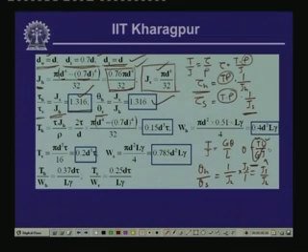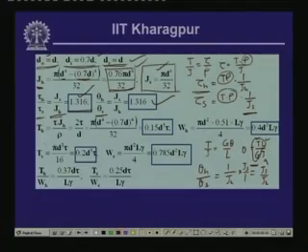So, both the ratios of the shear stress as well as the angle of twist depend on the polar moment of inertia of the shaft, and the value corresponding to that is 1.316 in both the cases, because both shear stress and the angle of twist depend on the ratio of the polar moment of inertia. So, now we compute the twisting moment, because we will have to compute the strength to weight ratio. So, we can compute the twisting moment that can be resisted by the hollow section and the twisting moment that can be resisted by the solid section.